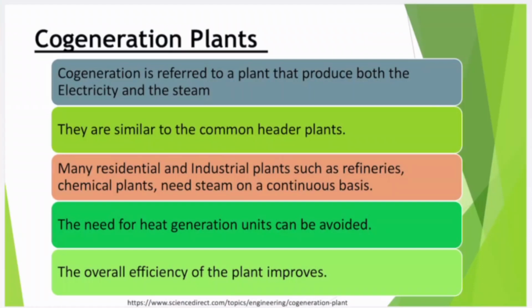So heat to electricity, electricity to heat will increase my loss, or the efficiency got reduced significantly, because if input output of heat to electricity is 70% and electricity to heat is 80%, then the complete system is operating with 60%, okay? Close to 60%, even below that.